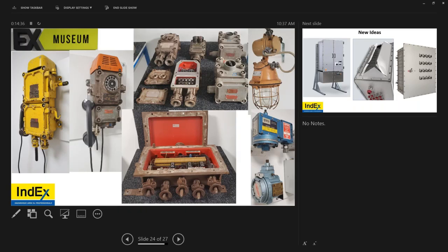What if we change a damaged bolt of an EXD enclosure with a non-manufacturer standard bolt, due to the manufacturer not supplying them anymore? Is this okay? If you have an old piece of equipment and the manufacturer's not around anymore, the best thing to do would be to talk to an EX consultancy such as ourselves, who can find you an EX repair shop, who would perhaps find you the correct bolt.